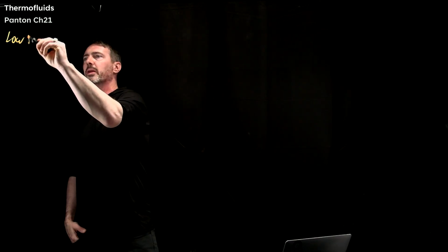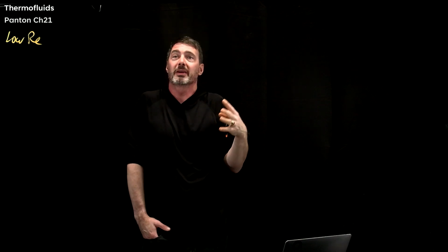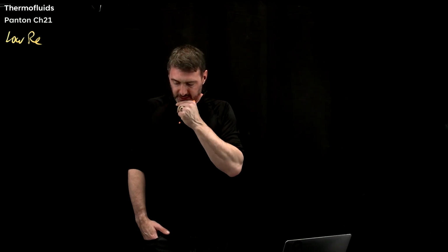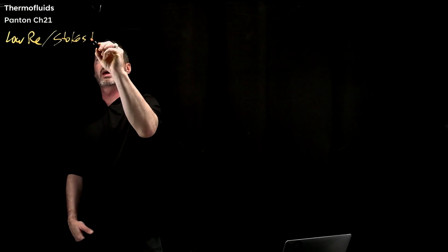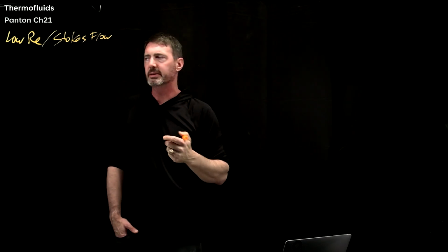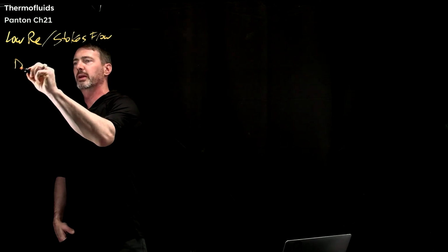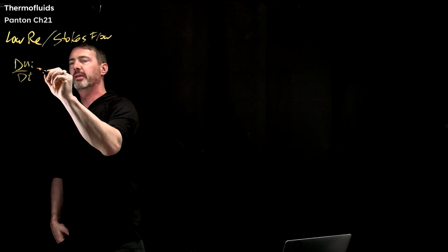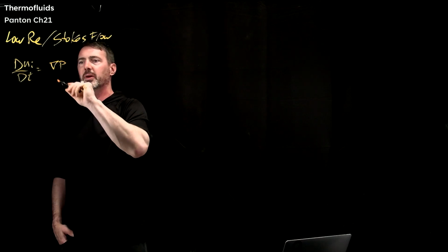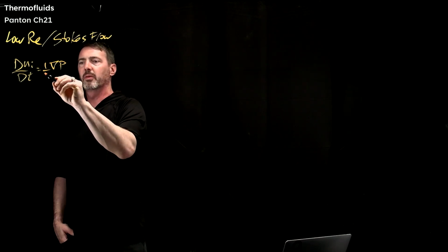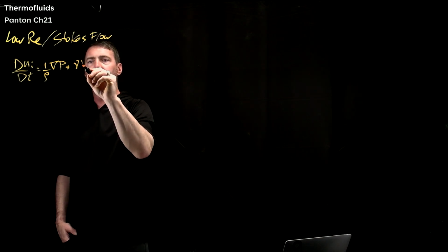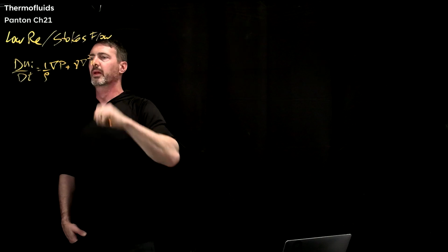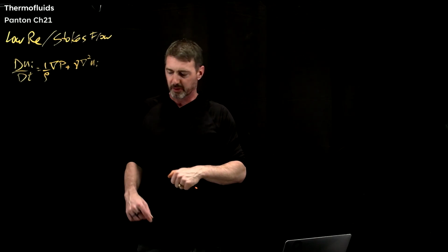Okay? And so what happens when you're at low speeds, or really low Reynolds numbers? This actually could just be normal speeds, but a highly viscous solution. So it's also called Stokes flow, okay? And what's going on is, let's start with du_i/dt equal to minus the gradient of pressure, where I've brought over 1 over rho here, plus nu del squared velocity. Okay, so this is a normal start, and I'm going to do a little bit of blackboard magic here.